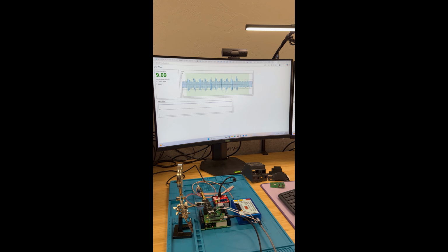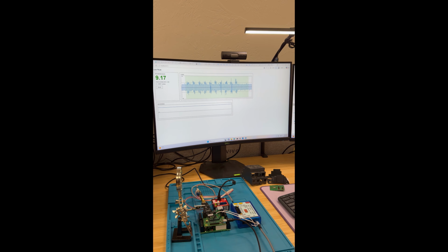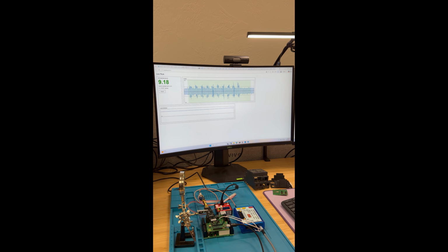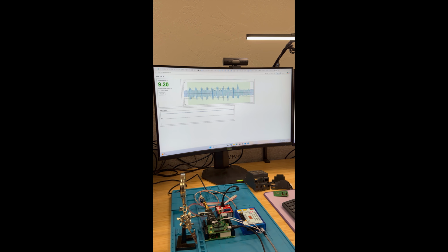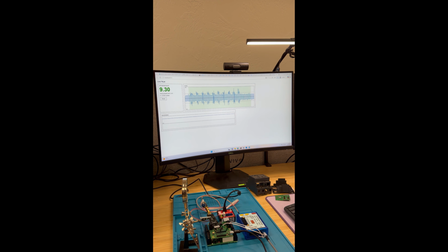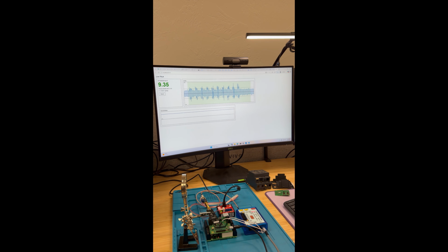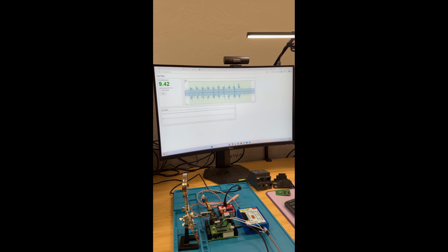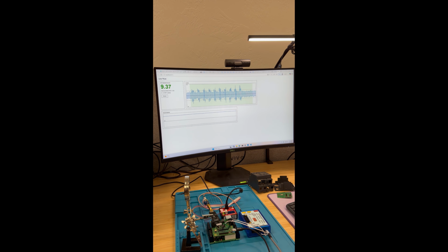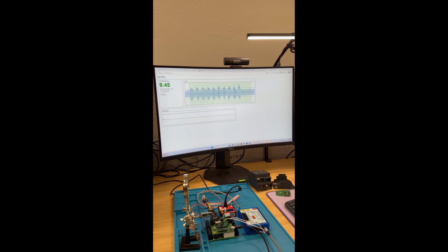A look at our live TVLA visualizer, which we use to find a hotspot on the chip. The leakage is incredibly sensitive and only localized to a very specific part of the chip, so we needed a tool like this to find it. In particular, we were using a 3-group TVLA, meaning we have 2 sets of fixed plaintexts and then 1 set of random plaintexts. We compare the first set of fixed to the set of random as our standard TVLA test, and then we also compare the fixed to the second fixed set as a null control to ensure capture order differences are eliminated.